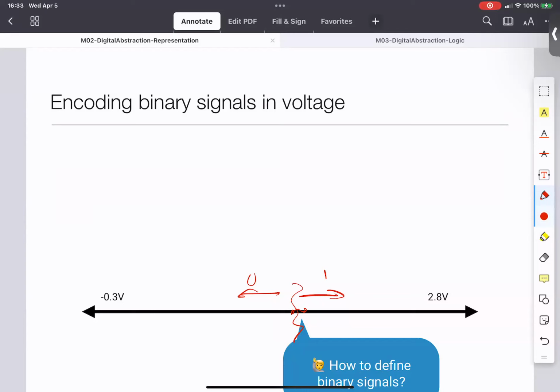There are all sorts of electrical equipment. Anytime you run your microwave or dishwasher, the voltage on your AC line at home jumps up and down, and these things then penetrate and get into your computers. If you monitor the voltage signal inside your computer, it's not stable. So there is noise, and this noise can cause this kind of a problem. So clearly, this strategy of just some threshold, left 0, right 1, is not very good.